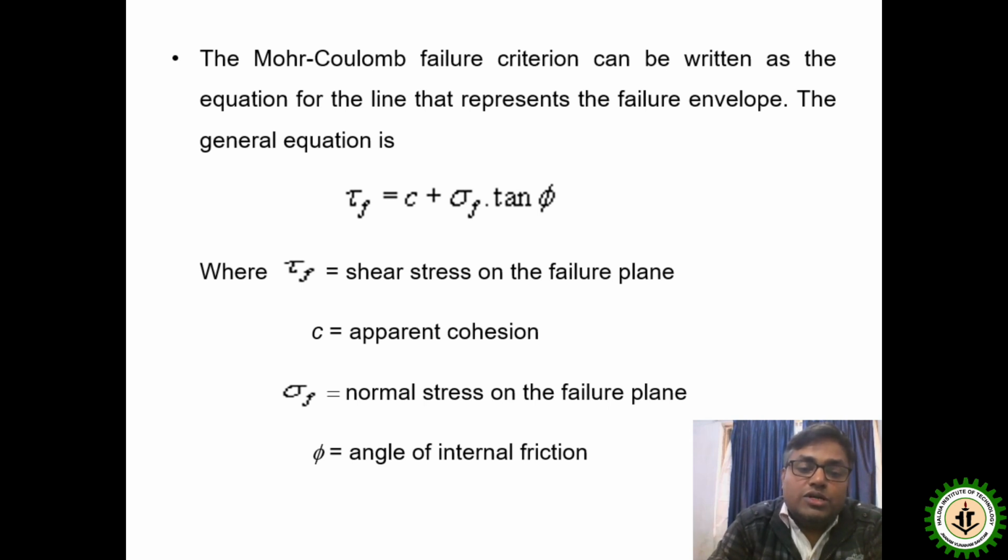Before failure of this mass, the shear stress will reach the maximum level, which is called the shear strength. In the field, during construction, when we construct the foundation, the normal load from this foundation acts as normal stress on the underlying soil.